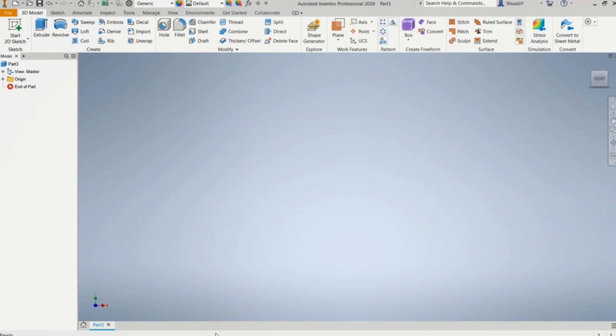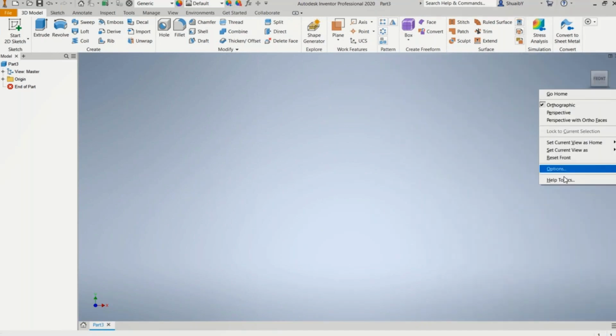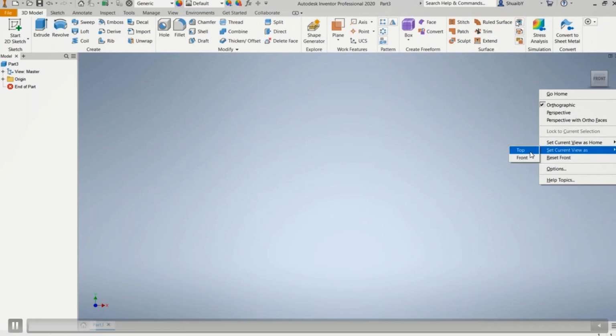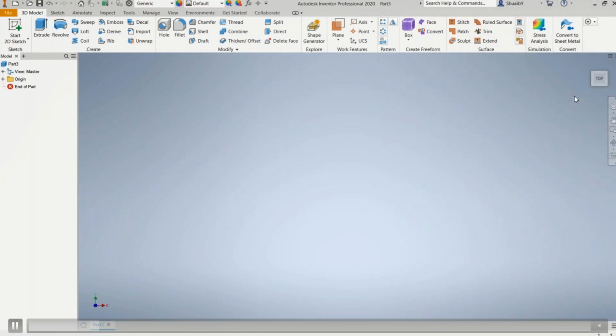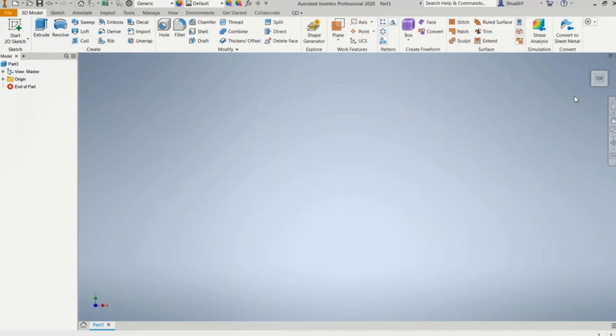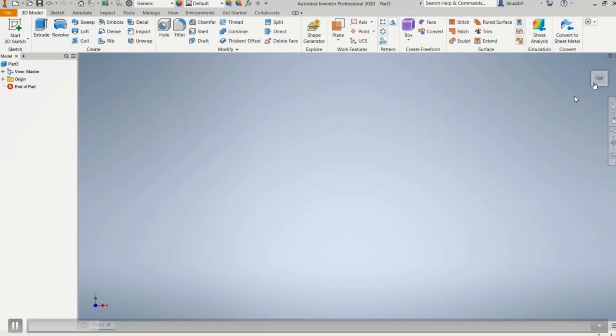Okay, now very important, on the left hand side, you see Y and X, and it's showing over there that it's actually the front view. That is incorrect. The reason why I say that is if you're looking from the top, that's what you would see. You would see a YX from the top. You wouldn't really see a front view. So this is actually a top view.